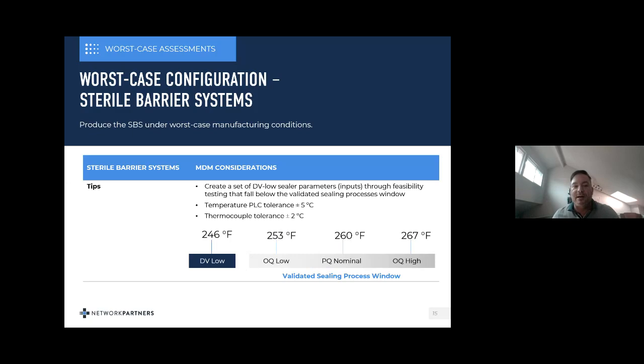There have been instances where I found through feasibility testing, on these used to work with 69-inch long catheters that go to your heart, the handle would cause some abrasion on the pouch and there'd be particulates all over. So I would actually use a backing card. They're really easy to use and update your design versus, let's say, a mold for a tray to make changes there. And create tabs that would cover certain parts of the device to mitigate the risk of puncturing the sterile barrier system.